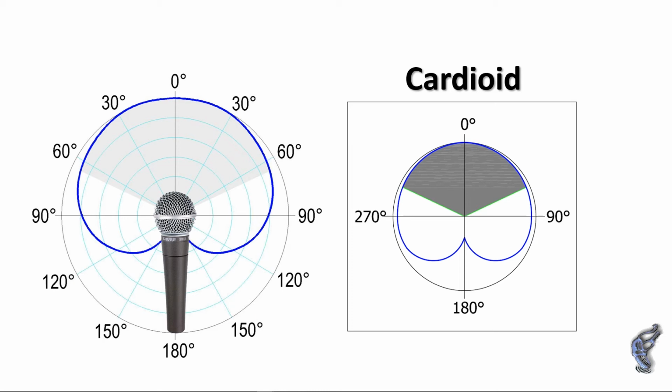The most common microphone we find in churches is a dynamic cardioid, like the Shure SM58 pictured here. It's overlaid on a polar response graph to illustrate where its pickup is the strongest and where it's designed to attenuate the sounds. Note that the pickup is actually in 3 dimensions. In this case, the best pickup is achieved speaking directly into the front of the mic, called 0 degrees on axis, and its maximum rejection point is 180 degrees off axis.